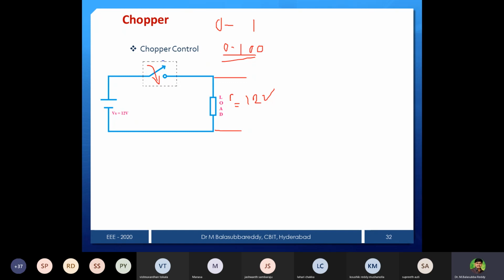First is the switch-on case. Now when the switch is off, what is your output? How is the switch turned off? Internally in this box there is a forced commutation circuit. Using that forced commutation, you are able to turn off the switch. The switch is off, meaning open, so the output voltage is 0. If you do that mechanism regularly, drawing the waveform is also simple, no?